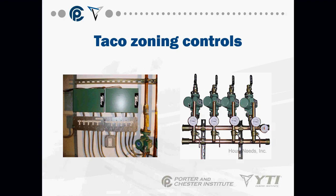But if you have a decent sized house and you have 1 circulator with valves, do you have a higher chance of having kind of cold spots at the further ends? You could. Yeah, you could. A way to kind of eliminate that is you raise the boiler temperature a little bit to compensate for whatever you're losing. But again, there's really not one benefit over the other. It's just really the application and what you're trying to achieve.